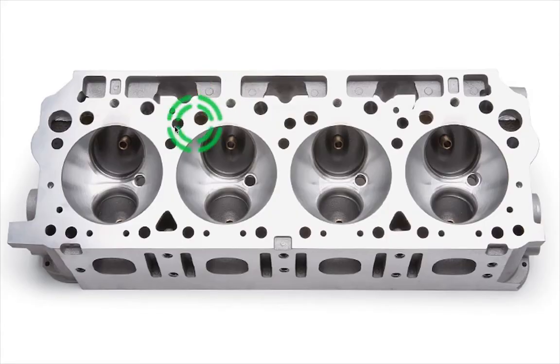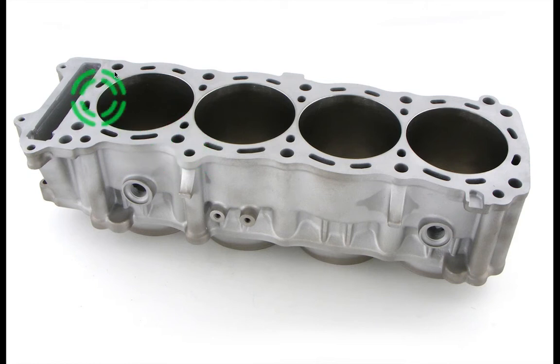Remember this part, I said it mates with your block. It sits right on top of this, right? But between them is a gasket, right? Which you must have been hearing all the time: gasket failure, head gasket. This is the gasket. This is a very crucial part, because your combustion chamber is this. When your piston reaches its max pressure at TDC, it's right here, right at the edge, right? So imagine it's compressing like 13 times or 10 times or whatever many times.